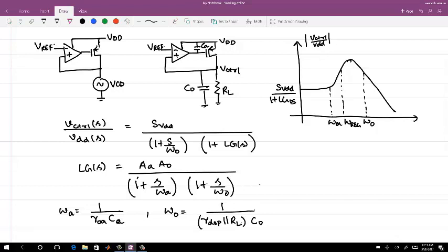So you have a peaking response, and if I want to change the peaking response for any transfer function, can you think of something I can do to omega A and omega O? Right now I made omega A dominant. I can make omega O dominant also. Omega A comes in the zero also; omega O doesn't. So depending on which pole is dominant, this becomes omega A, and then somewhere you have omega O. If the blue curve is for when you have this change in the dominant pole.